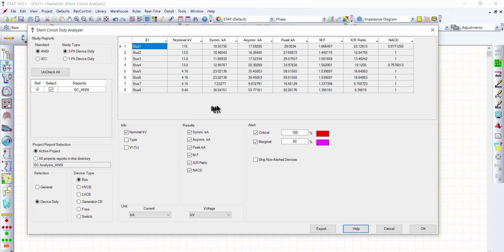So from here, the bus bracing, the short circuit withstand capability of our bus bar, is a minimum of 25% higher than the actual short circuit on the power system. Here, we have already resolved the issues on the buses.